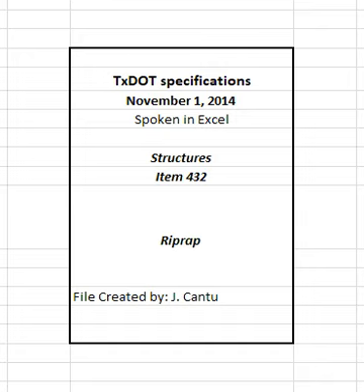3.3 Pneumatically placed concrete riprap, Class II. Meet Item 431, Pneumatically Placed Concrete. Provide reinforcement following the details on the plans and Item 440, Reinforcement for Concrete. Support reinforcement with approved supports throughout placement of concrete. Give the surface a wood float finish or a gun finish as directed. Cure the riprap with membrane curing compound immediately after the finishing operation in accordance with Item 420, Concrete Substructures.